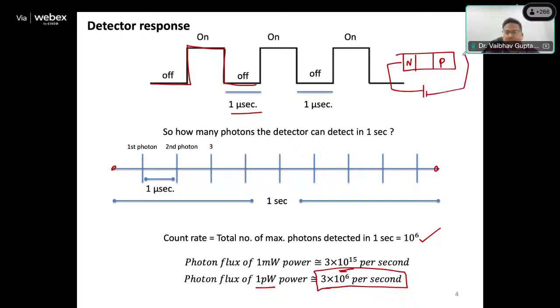And you know that as soon as you apply negative reverse bias, there is a field here. And because of this field, suppose a photon comes, and then an electron-hole pair is generated. So the electron will travel here with a drift velocity, and this field will also support it. So it will take some time to cross this barrier. Then the next will be the diffusion velocity, right? So again, there will be some time associated with it.